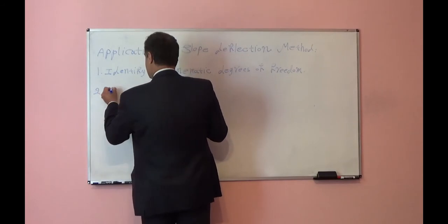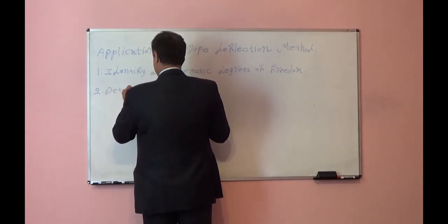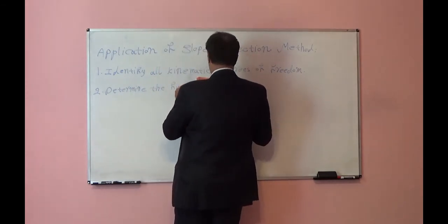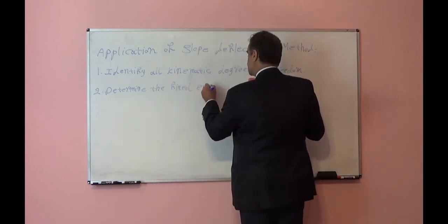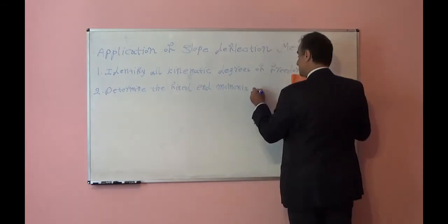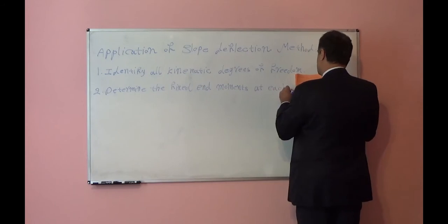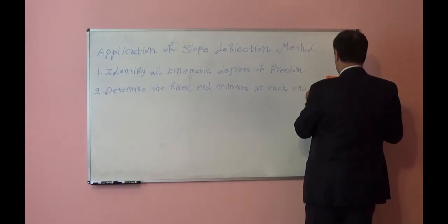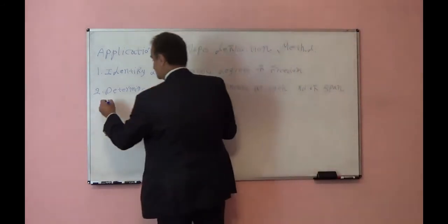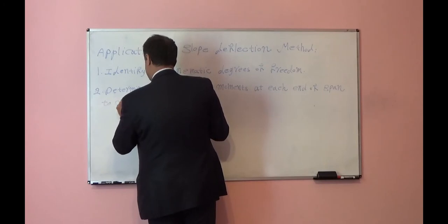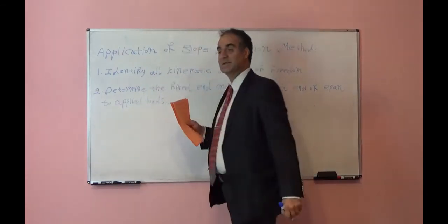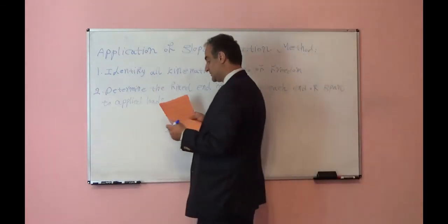Second, determine the fixed end moments at each end of span due to applied loads. It means fixed end moment, and we will find those using tables.